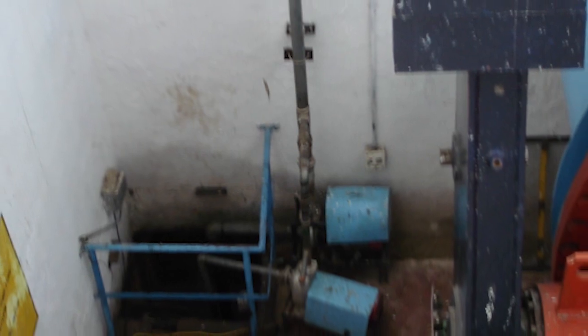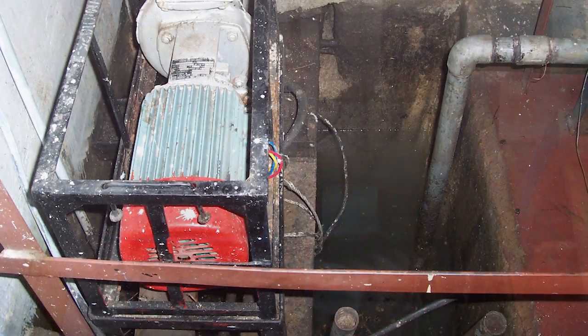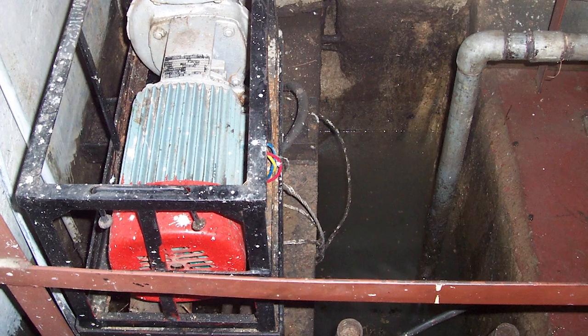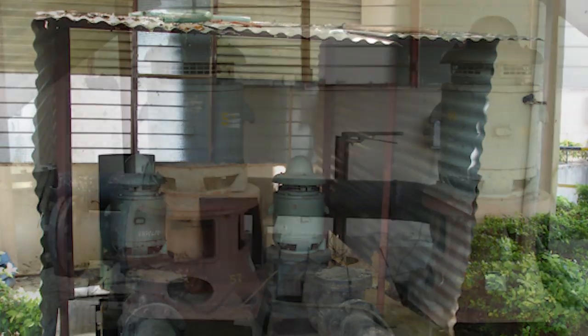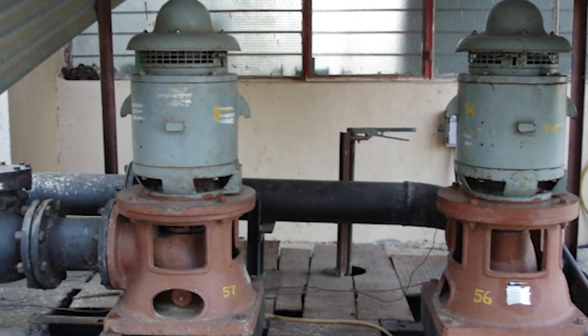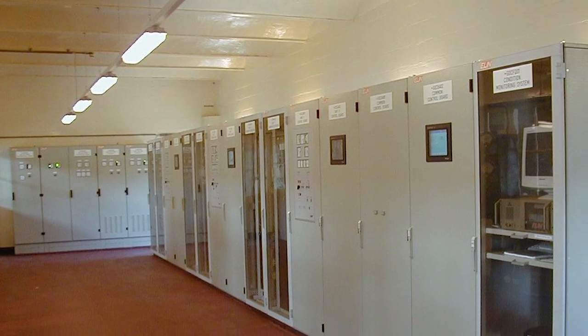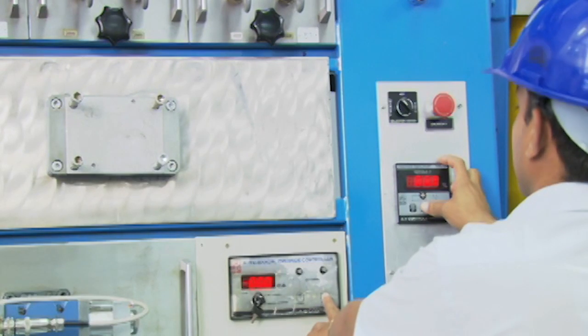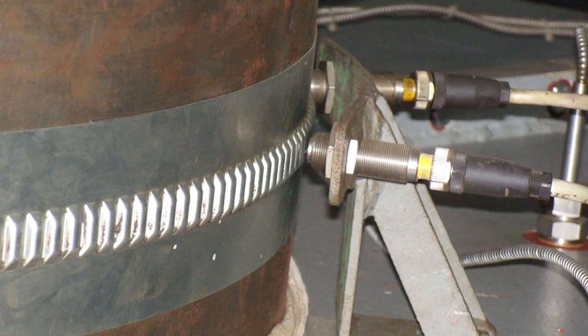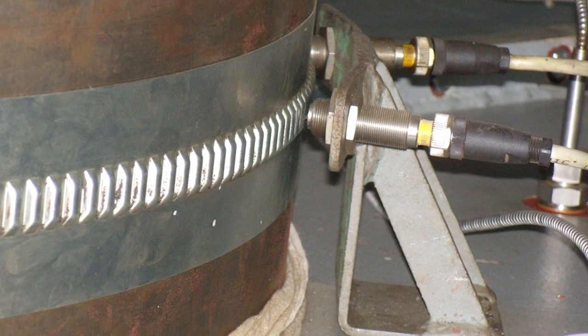Drainage and dewatering system. It is designed for drainage of all water discharge outlets, returns, drainage from equipments, and any seepage from submerged wall of powerhouse. Other systems are also required for proper working of a power plant, which include turbine governors. They regulate the speed and output of turbine generator units by controlling the water flow through the turbine by adjusting the opening of wicket gates or nozzle.